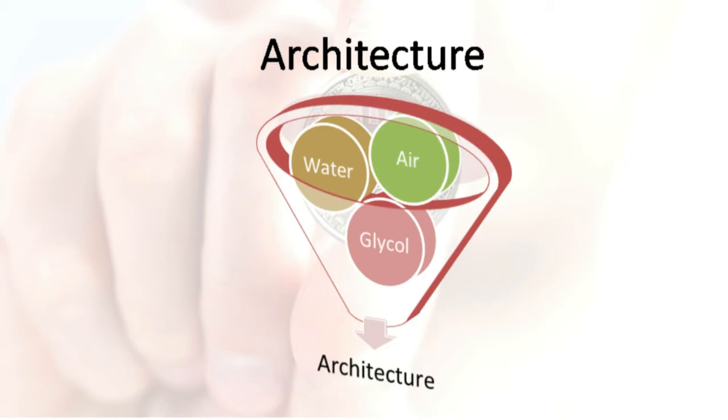In the most simple configuration, we will use 2 heat exchangers, where the first one removes the heat from the air and transfers it to the refrigerant, and the second heat exchanger removes the heat from the refrigerant and transfers it back to the space with the mining rigs while the heat is transferred to the outside air. The 3 most common architectures are the air-cooled, the water-cooled, and the glycol-cooled.